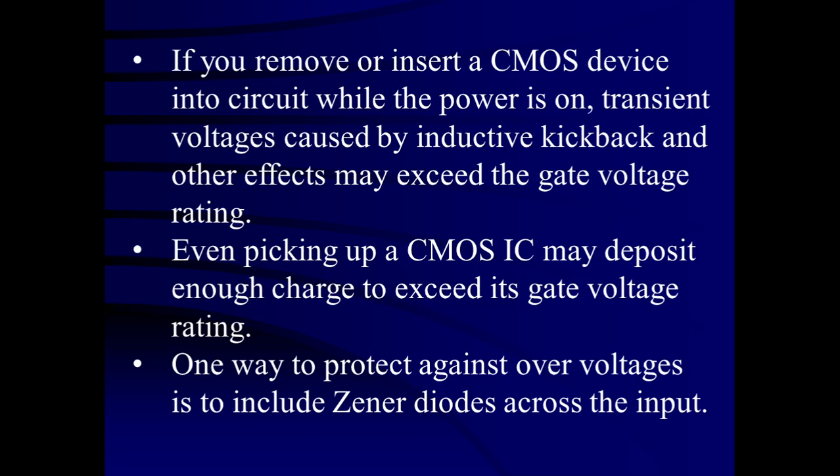damage the gate. Even picking up a CMOS IC may deposit enough charge to exceed its gate voltage rating, because when you pick up a CMOS IC, its gate will be in touch with your body, and the charge from your body can be deposited on the gate of a CMOS IC, which will damage the CMOS inverter, because a larger amount of charge will be deposited on the gate, and hence the insulating layer is also going to have more negative charge.